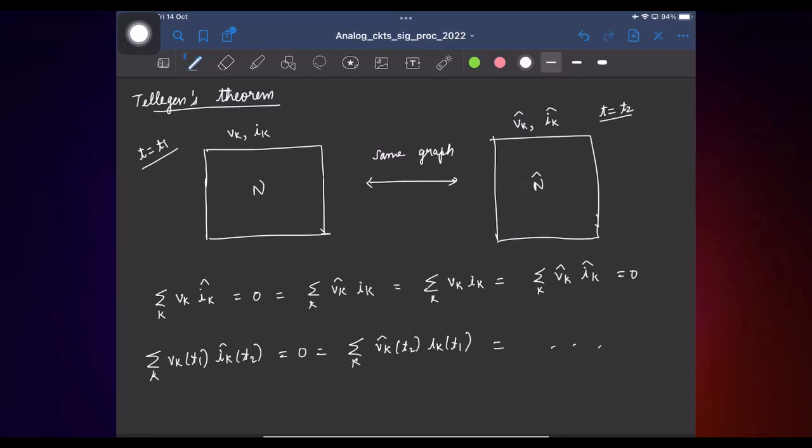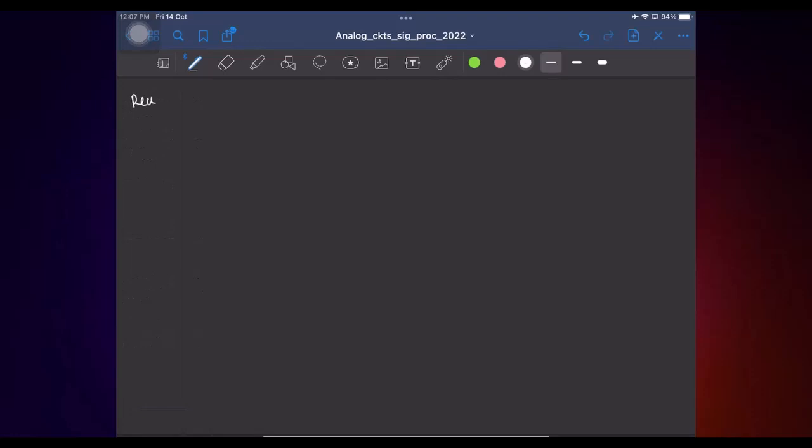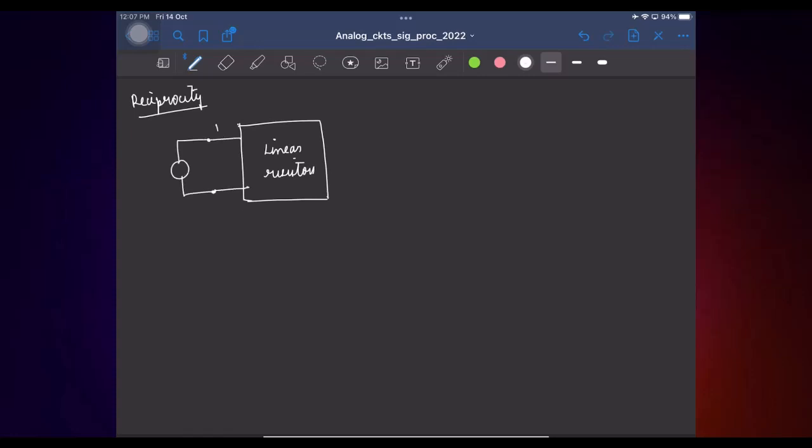And using this Tellegen's theorem, we proved or looked at the principle of reciprocity, and we looked at the case for a network containing only linear resistors. So let's say we have a network containing only linear resistors. If I apply a voltage at this port 1, I'll call 1 prime. So this voltage is V1. This is 2 prime, and I measure a voltage here V2. Now I can get the same response by taking the same network, by applying a corresponding excitation at the second port and measuring a response at the port 1.